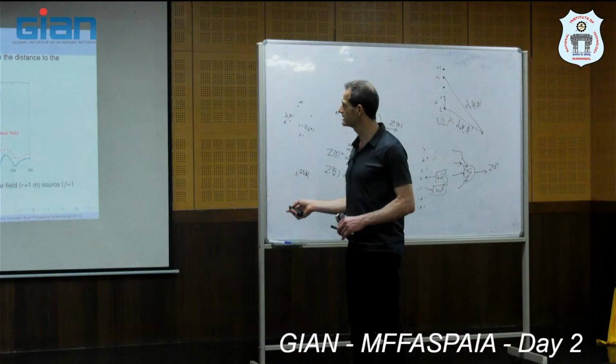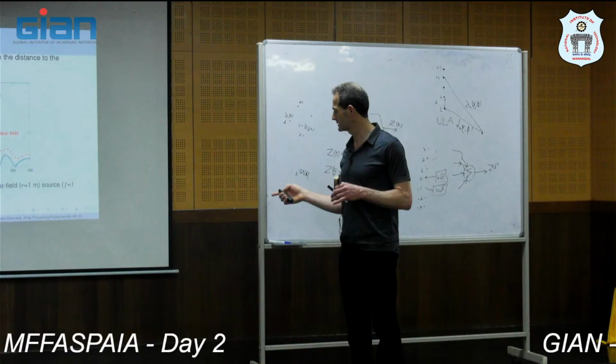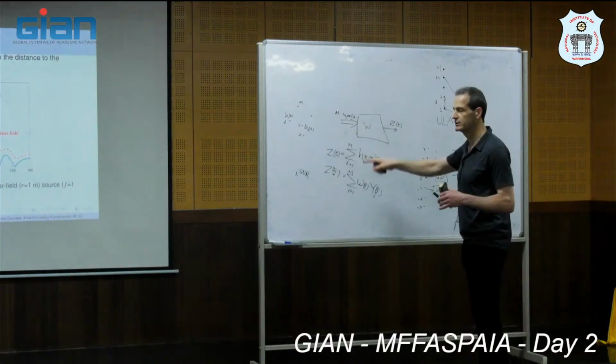So we see that for this near field source, it doesn't go to 0 for any direction, because you cannot cancel exactly. Why do you think we cannot cancel exactly in this case? So we have 11 sensors. What do you think? What made this situation that you cannot cancel the source that comes from any direction? The summation of the signals with constant weight, they cannot cancel each other.